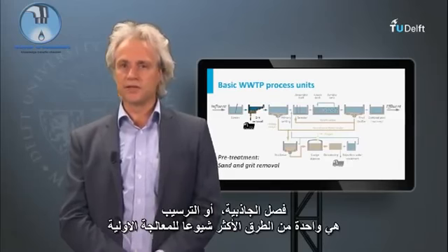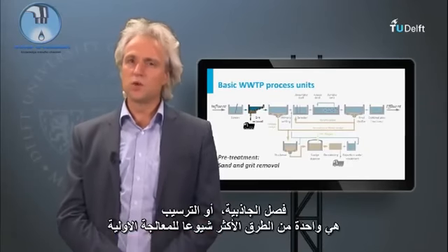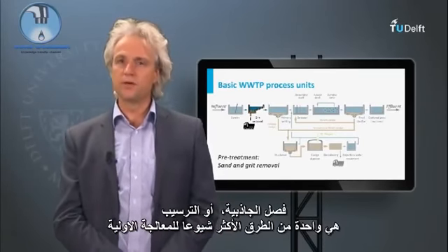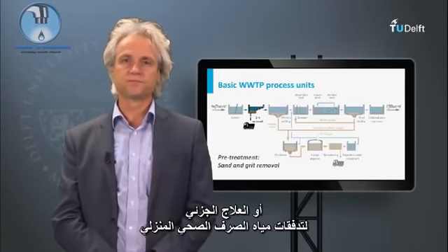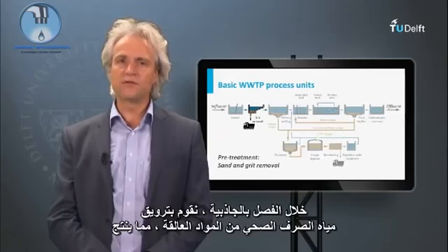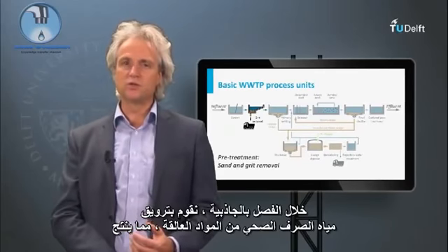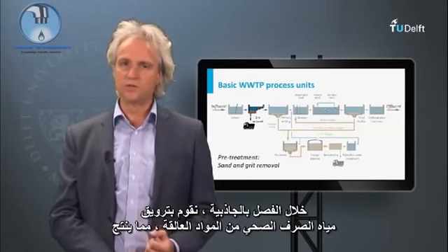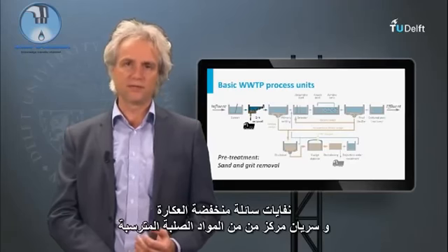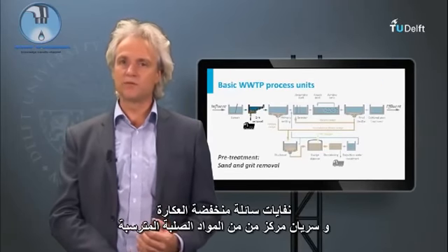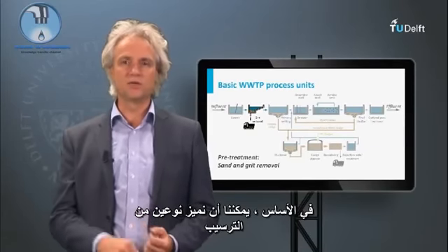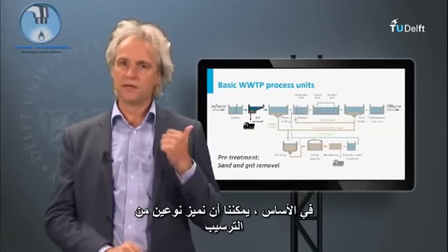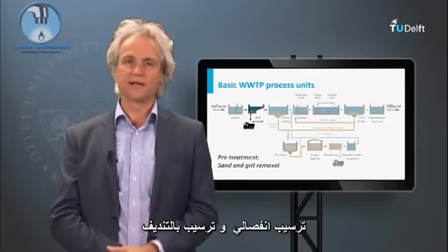Gravity separation, or settling, or sedimentation, is one of the most common approaches to pre-treat or partially treat the domestic and municipal sewage flows. During gravity separation, we clarify the sewage flows from suspended matter, resulting in low turbidity liquid effluents and a concentrated stream of settled solids. Basically, we can distinguish two types of settling: discrete settling and flocculant settling.